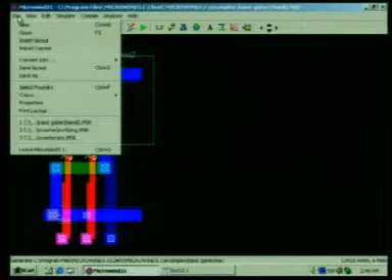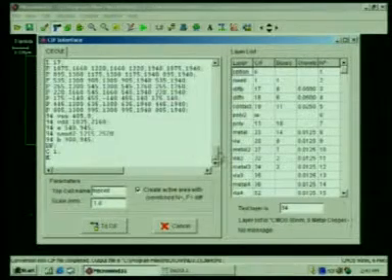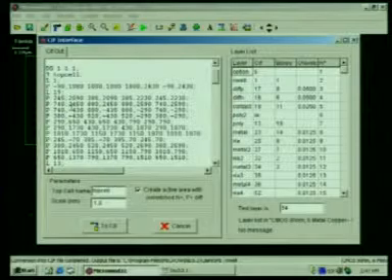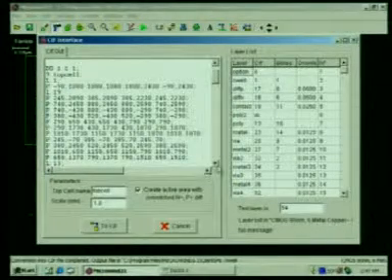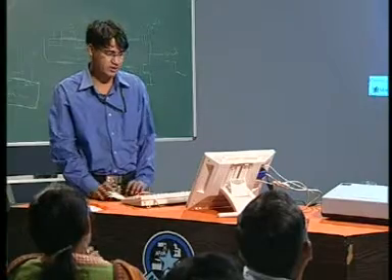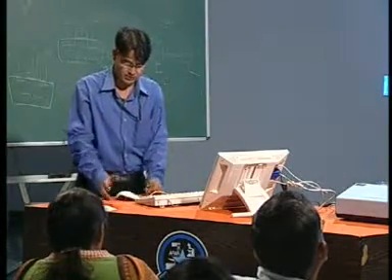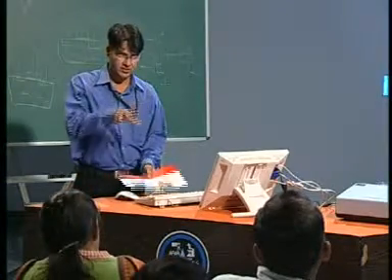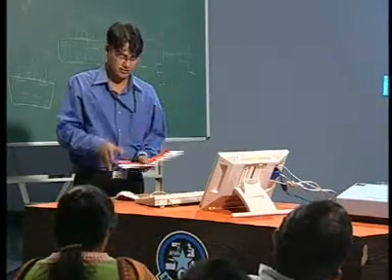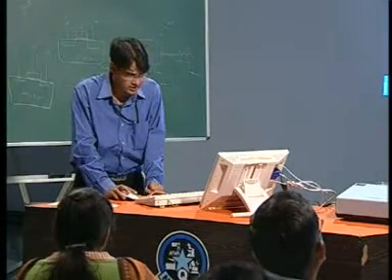And another thing that we call CIF layout. This CIF layout is the file we have to send to the foundry. Actually these are the geometric locations of your basic MOS, different kinds of masks, metal layers. So just create this and send this to the foundry. After that this file will be read by those specific tools, that is under the wafer stage we call that, and this is the chip, and that tool will read this file, totally controlled by computers, and all the masks will be generated on that chip. After that we will go for proper routing and placing. So this is the method actually.